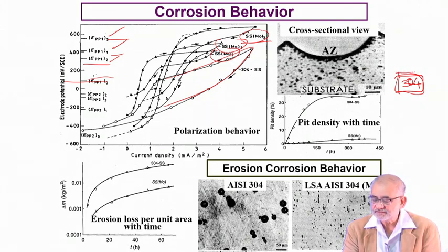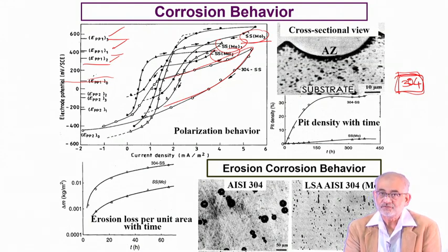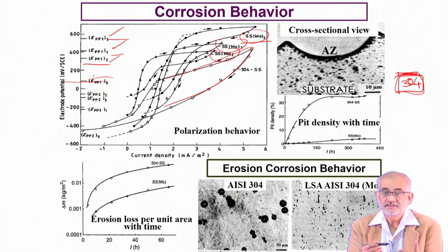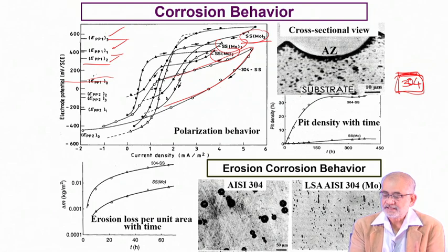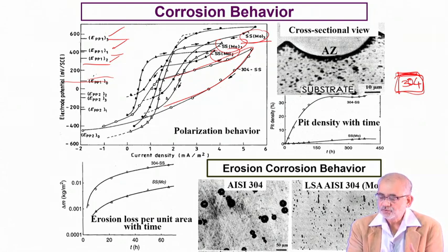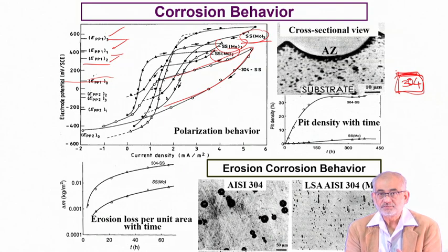But instead, if you can just alloy the surface with an adequate amount of molybdenum and retain more molybdenum than what is allowed by equilibrium processing, you make the surface fairly resistant to pitting corrosion. And this is possible on a finished component, fairly fast, maintaining all dimensional accuracy, and most importantly creating a microstructure which is not possible by equilibrium processing.